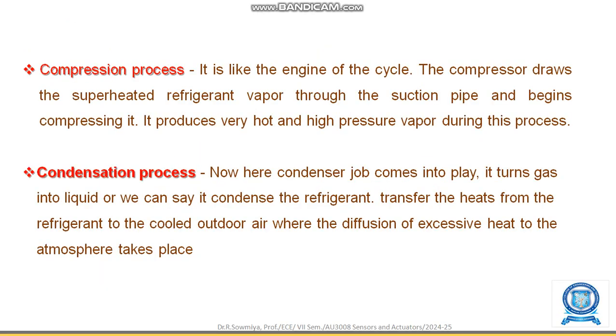Compression process, it is like the engine of the cycle. The compressor draws the superheated refrigerant vapor through the suction pipe and begins compressing it. It produces very hot and very high pressure vapor during this process. Condensation process.